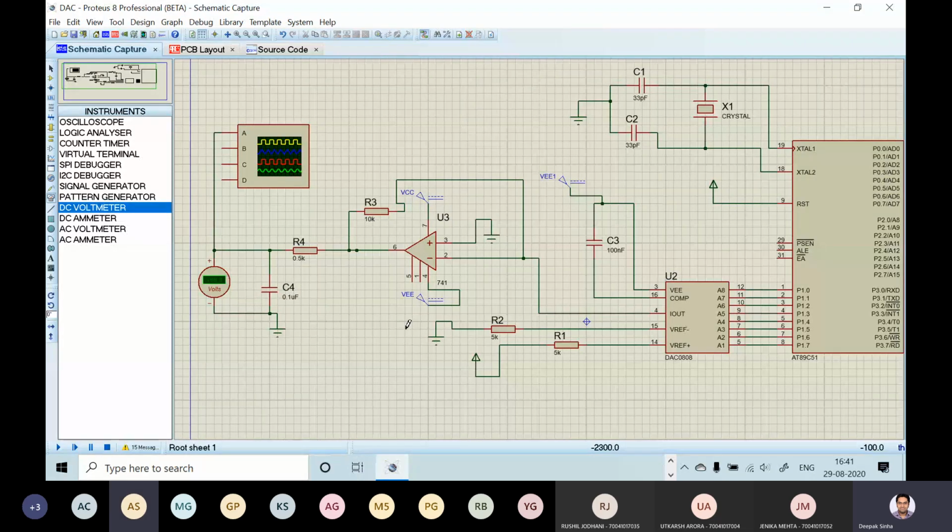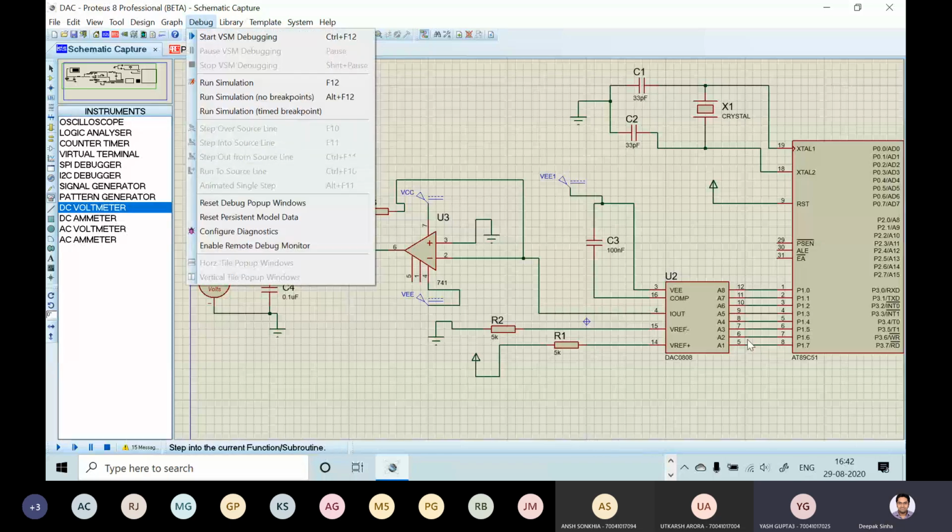So the oscilloscope is open, but it is not showing the graph. Are you getting any voltage? Attach a voltmeter over there and check it. Yes sir, voltage is there, but my graph is coming a bit strange. What is strange? The steps are visible but they are very small, like first there is a big step, then they keep getting smaller. Yes, so did you reverse the connection?